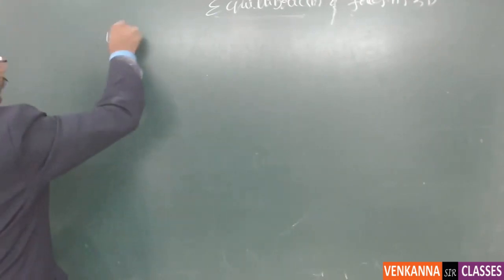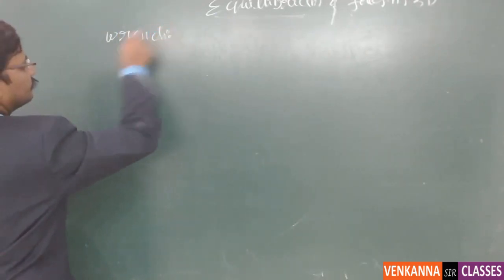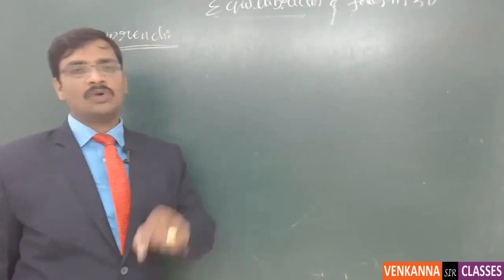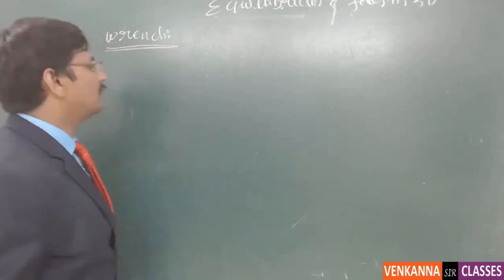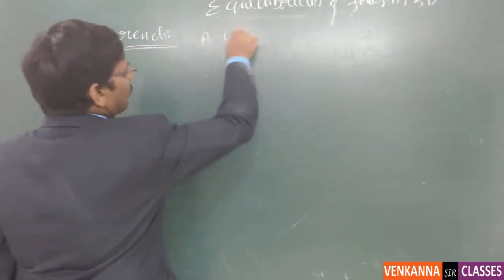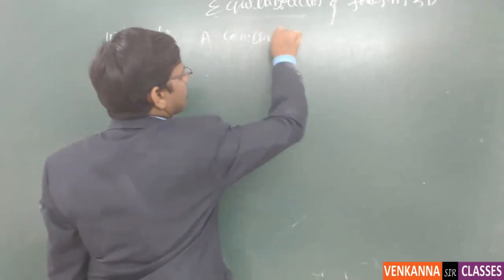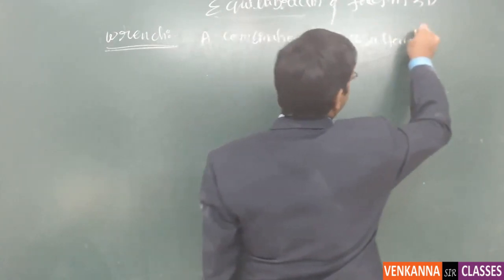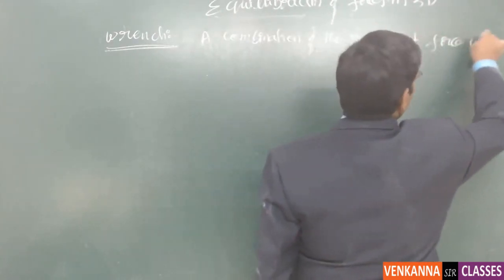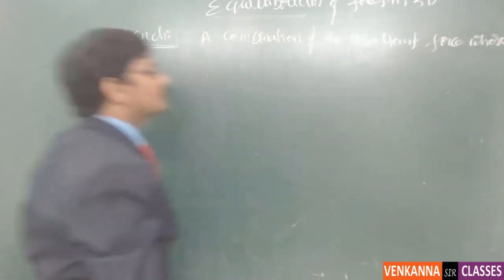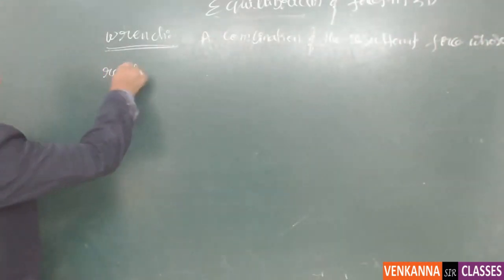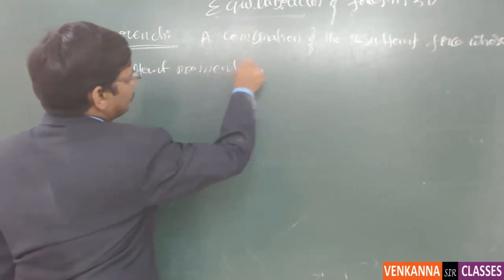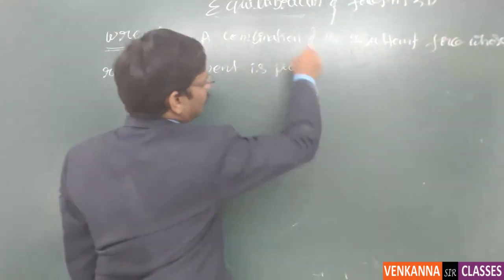So there is a concept called wrench. This wrench concept is just what I have explained. A wrench is nothing but a combination of the resultant force whose resultant moment is parallel to the resultant force.